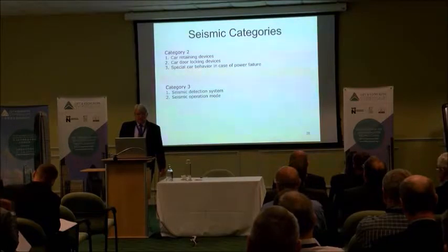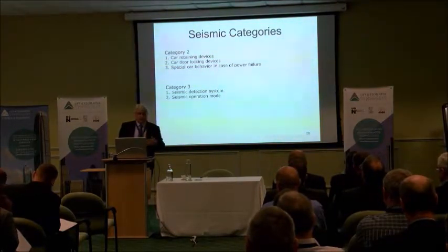You have to have a seismic operation mode. The one I'm most familiar with is in California. We shut down the elevator completely, and then if everything is still able to run, we move the car to the nearest landing, moving in the opposite direction of the counterweight so they don't collide.